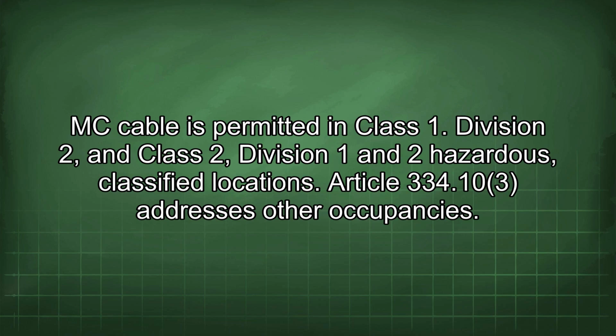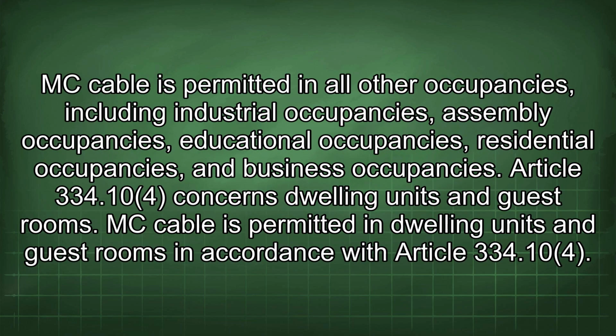334.10(3) addresses other occupancies. MC cable is permitted in all other occupancies, including industrial occupancies, assembly occupancies, educational occupancies, residential occupancies, and business occupancies.